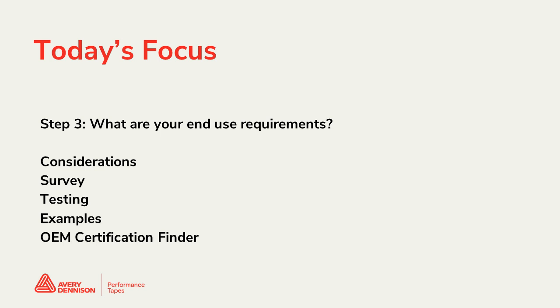In step 2, we're considering what type of substrate the converted part would be bonding to, and the main factor for that would be surface energy and determining the best combination of adhesive to work for those two materials. And now step 3 is really understanding what's going to keep your part bonded and selecting the right tape to make sure that the part will stay bonded for the life of the end-use application.